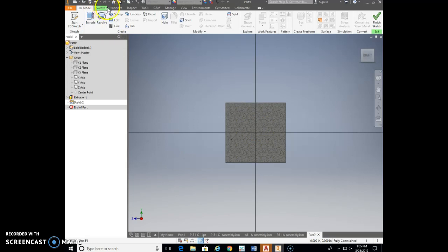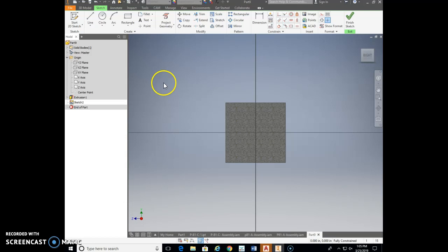A couple different things you can do there. One is you can go to this tab, which is the Sketch tab. You can go Project Geometry. The same as what we did just a moment ago in this origin list. There's one down there called Center Point. I can click on it and re-project my origin. Or, a better habit to get used to is when you delete, just don't put a big window around everything and delete everything. Maybe delete things like that. So you just select those lines I need to delete, and I did not select my origin to delete.